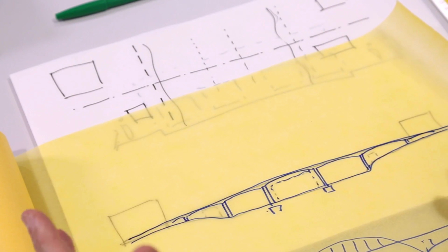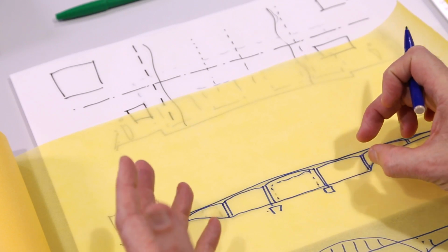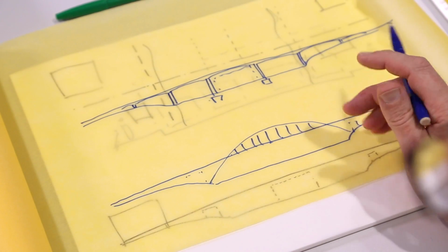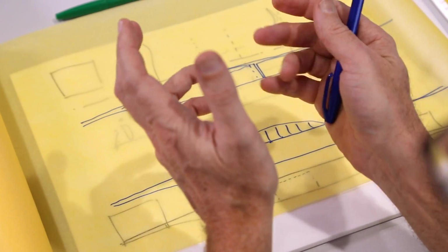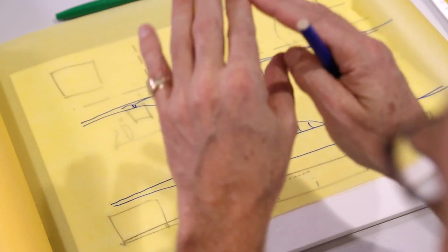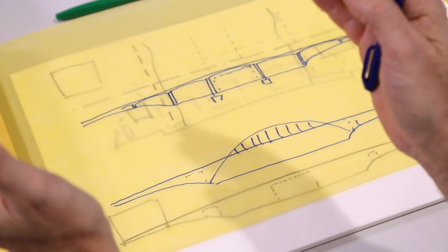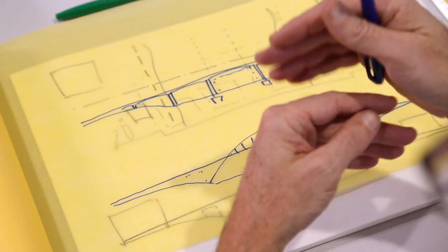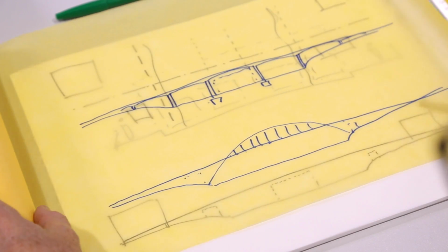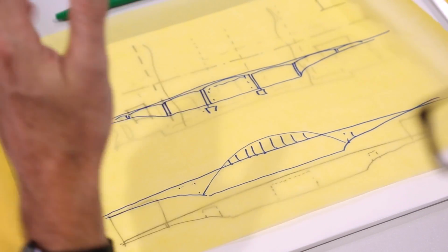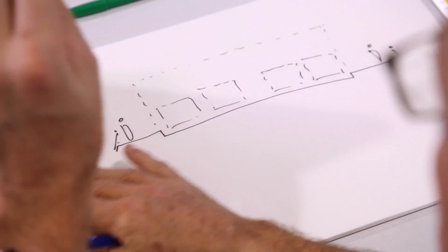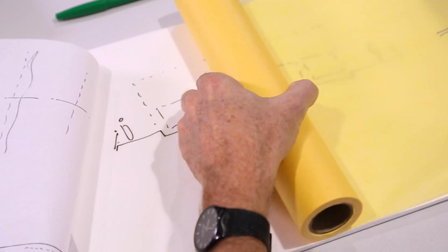Yep, very simple. And that depth is a different sort of depth to the depth we had in the arch solution. By and large, I tend to look at the depth being something like 1/20th or 1/30th of the span, something in that sort of range, depending on whether we have continuity or not. A continuous beam, you might have 1/30th of the span. If it's a simply supported beam, it might be rather more. It's a 1/20th. But of course, thinking about the cross-section now, going back to my cross-section diagram, I now need to think about where does that depth materialise.